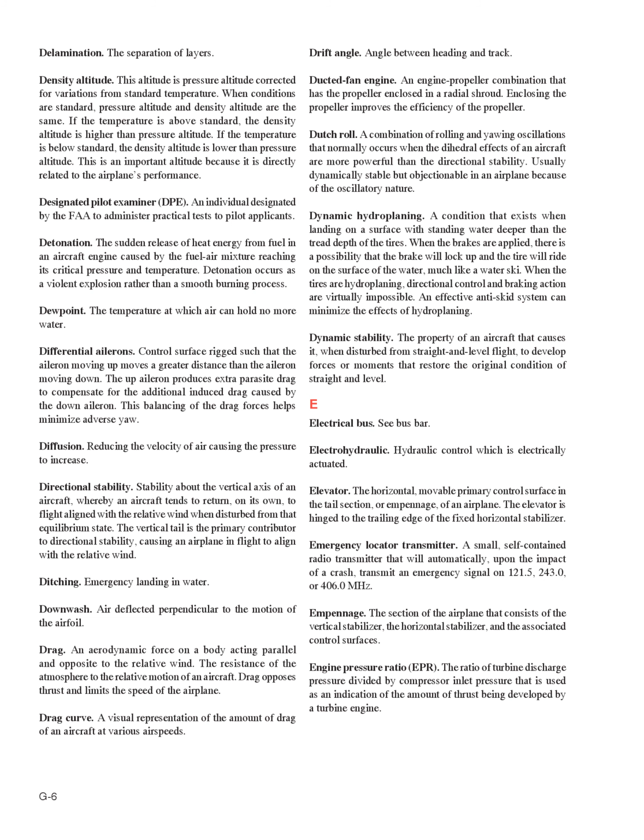Emergency locator transmitter. A small, self-contained radio transmitter that will automatically, upon the impact of a crash, transmit an emergency signal on 121.5, 243.0, or 406.0 MHz. Empennage. The section of the airplane that consists of the vertical stabilizer, the horizontal stabilizer, and the associated control surfaces.